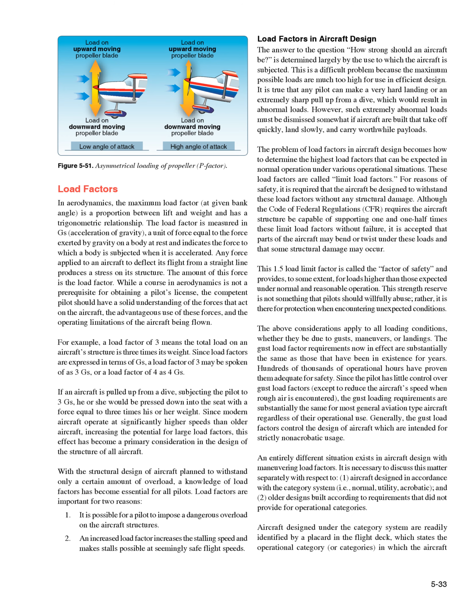Load factors in aerodynamics. The maximum load factor, at a given bank angle, is a proportion between lift and weight and has a trigonometric relationship. The load factor is measured in G's, acceleration of gravity, a unit of force equal to the force exerted by gravity on a body at rest, and indicates the force to which a body is subjected when it is accelerated. Any force applied to an aircraft to deflect its flight from a straight line produces a stress on its structure. The amount of this force is the load factor.